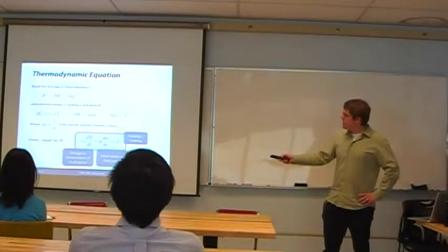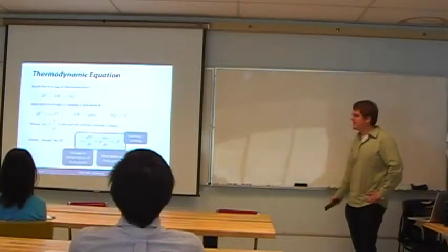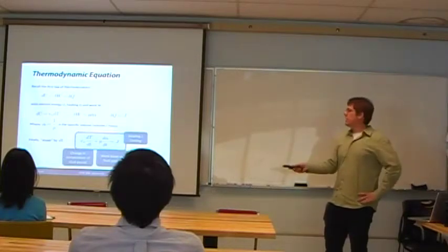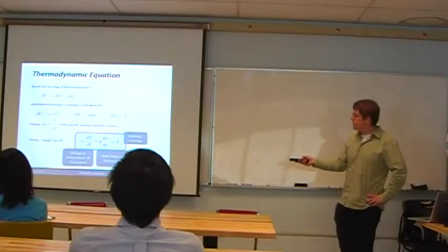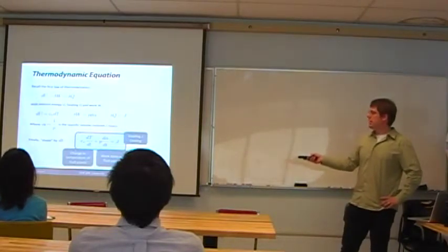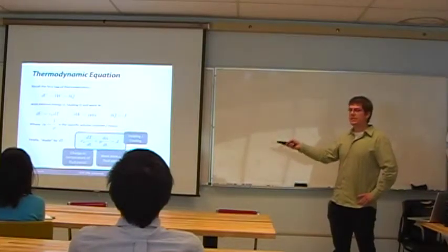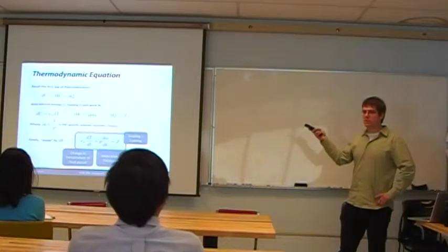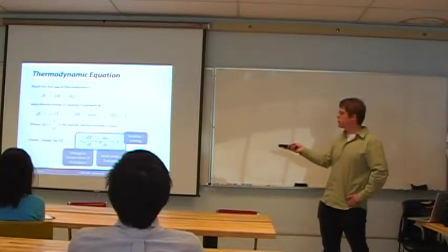So if we take this expression, we'll perform these substitutions and then divide through by dt. Divide, in this case, again, hand wavy. We obtain that the change in temperature of the fluid parcel plus the work done on the fluid parcel is equal to heating and cooling. But this expression that we derived associates all the state variables that we know already and provides a corresponding closure.